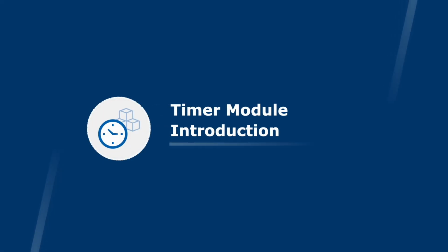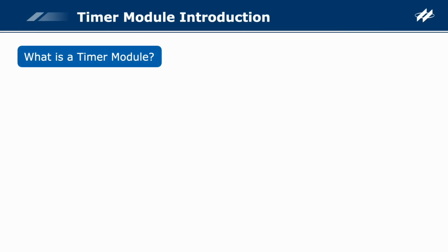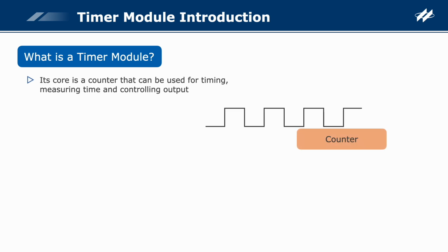Timer Module Introduction. In MCU programming, the implementation of functions is often inseparable from timer modules. So what is a timer module? Its core is a counter that can be used for timing, measuring time, and controlling output.